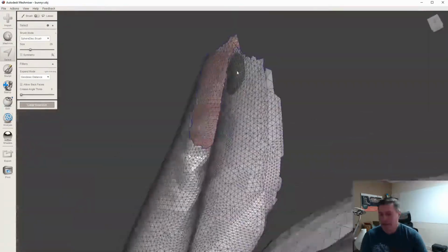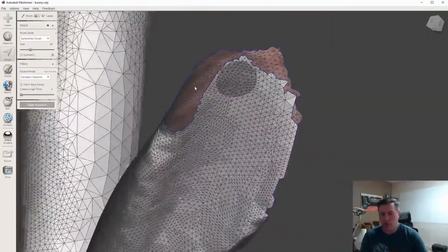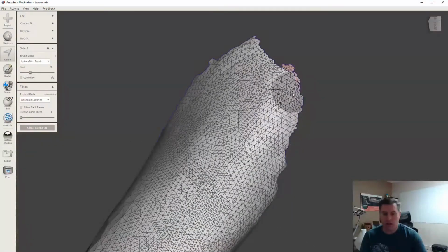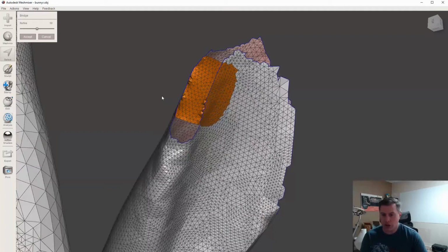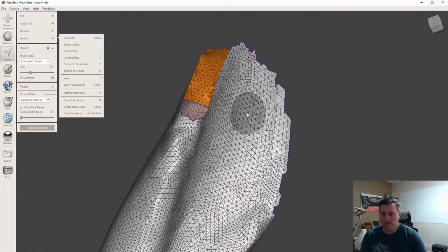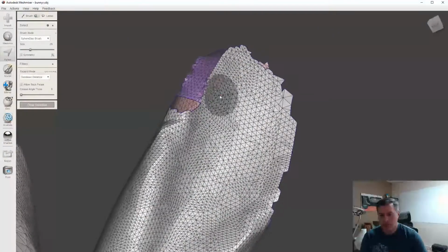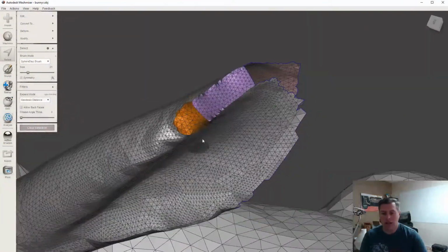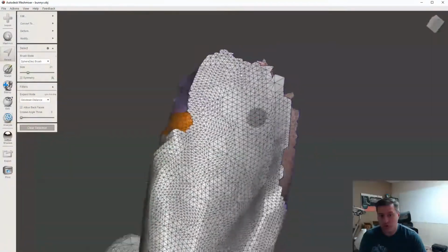You can kind of break this into 3 different areas for any of these problem meshes. And if you click on one side and click on another, you can do a bridge command like that. And what that does is the bridge command now makes this area into a hole that is much more easily filled if you press the F key. So that is one technique of using the bridge command to break up complex holes into sections that you can fill with the more traditional tools.